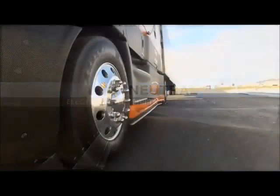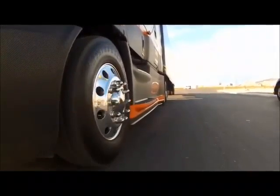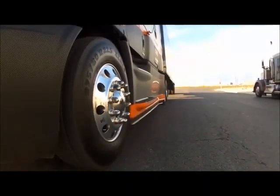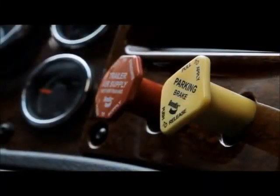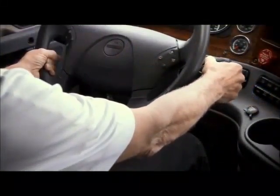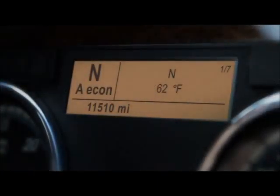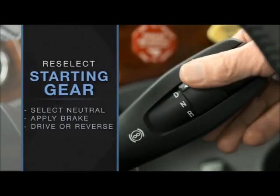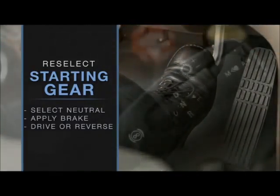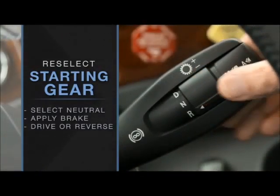An auto-neutral feature electronically shifts the transmission into neutral if not done within 5 seconds after the truck parking brake is applied. An audible warning instructs the driver to select neutral. If the driver forgets to put the vehicle in neutral, a second audible warning tells the driver the transmission has selected neutral. To reselect a starting gear, just move the transmission select collar into neutral and then into drive or reverse with the service brake applied.